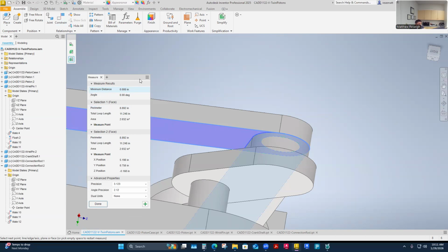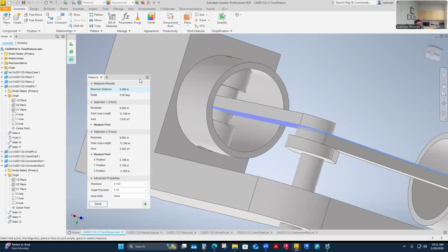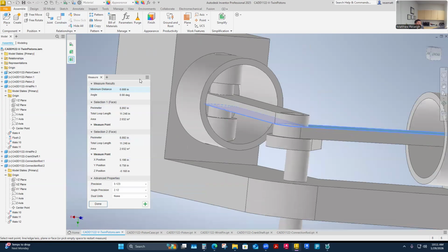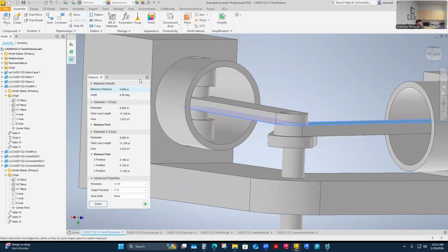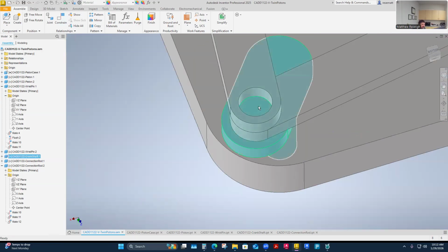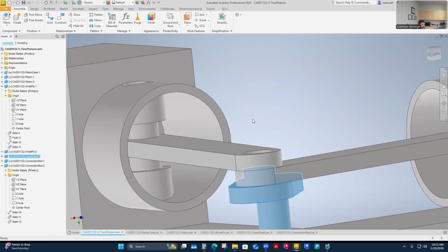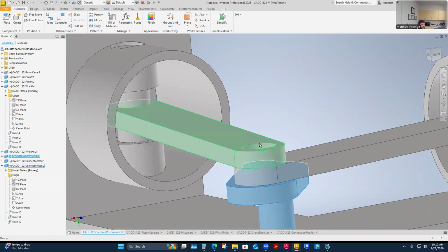If they're more than zero, it just means that one of these piston centers is higher or lower than the other one, and it's probably that 1.03125 dimension that is driving that. It's how high I put this off from here up to the center of the door. It really mattered, right? Now that I have two together, they have to be at the right height distance. So the only thing is I don't have any way to grab. I mean, this shaft needs to be extended up through here. And it needs to be extended not just through to flush, but through so that I can also put a fastener on it to hold it.